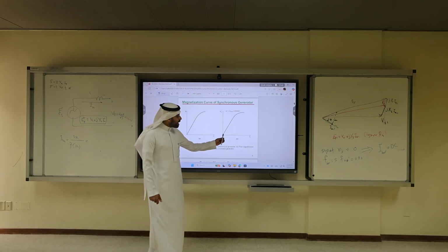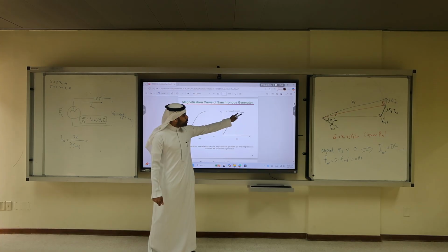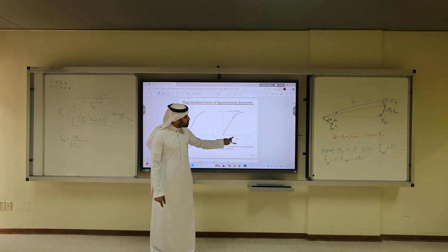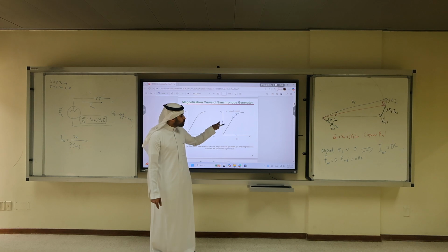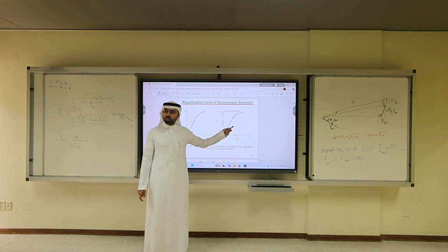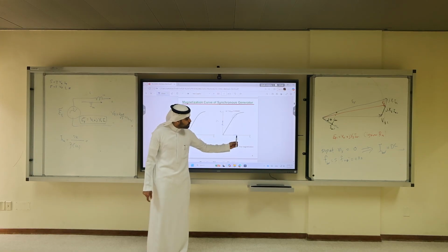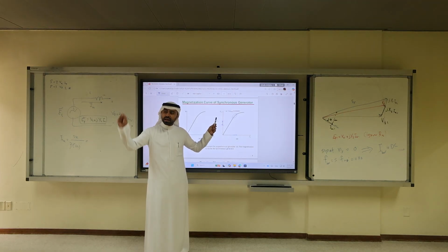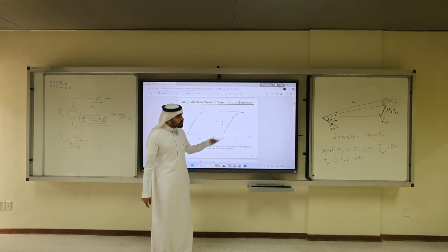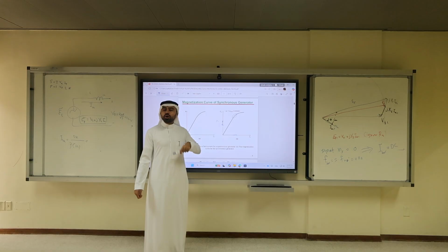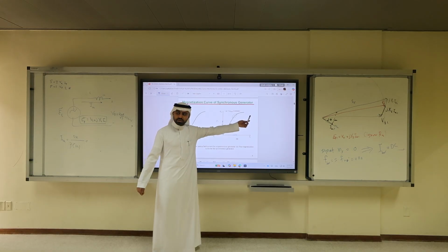If I increase IF, where do we operate? Do we operate in the saturation or in the linear region? Linear, high linear, just before the knee. So if I increase this by 20%, what will happen to EF? Increases, also by 20% from the curve. You understand now? If I increase the field by 20%, I increase the excitation voltage by 20%, if and only if I'm in the linear region. If I'm in the saturated region, this is false. And no one will operate the machine in the saturated region.